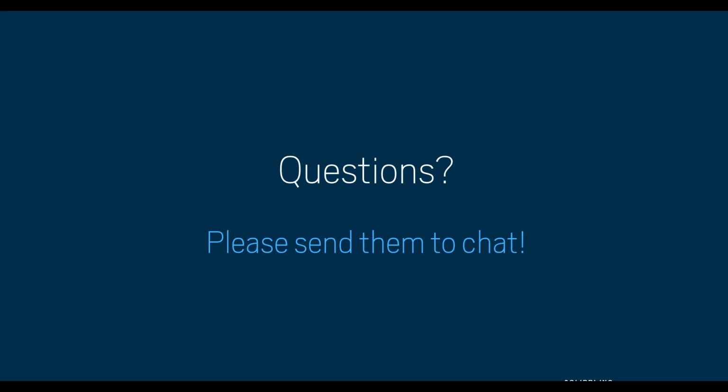Okay. Then the next one is, how do you check the specifications of an element for the requirements in IFC or in another way? There are several ways to do it. You can use rules for it, but one of the fastest is to make an information takeoff that shows you in columns the data that you have required in your project. And then in the printout or in Excel, you can see that everything is there and correct. That would be the fastest way.